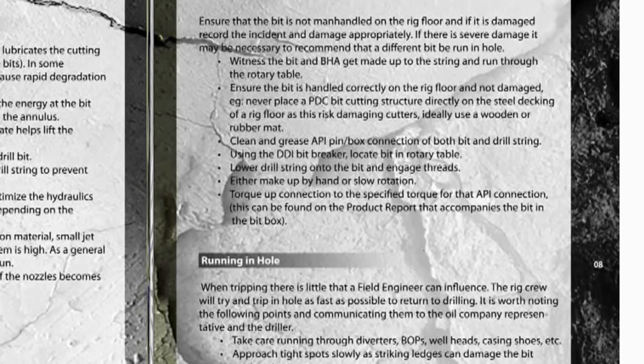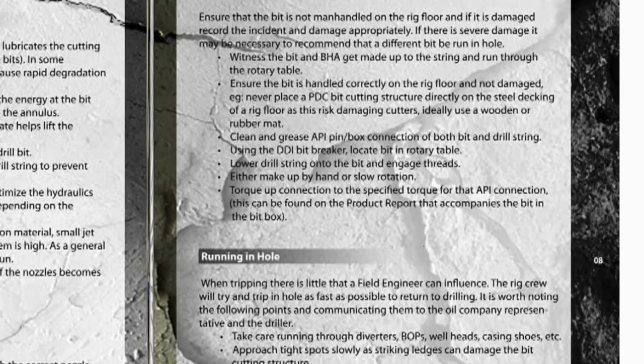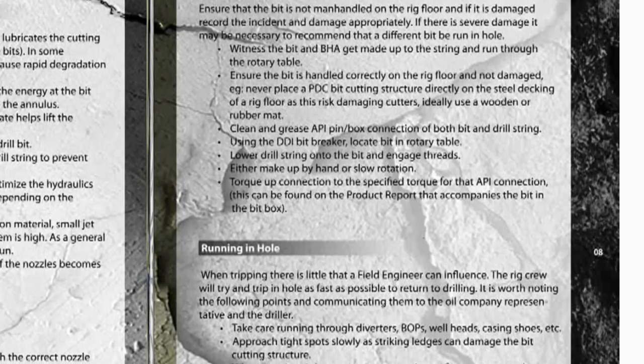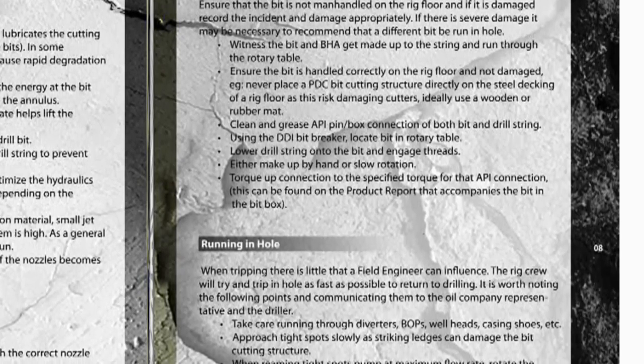For example, never place a PDC bit cutting structure directly on the steel decking of a rig floor, as this risks damaging cutters. Ideally, use a wooden or rubber mat.